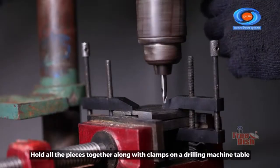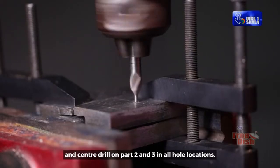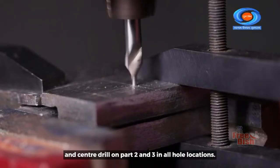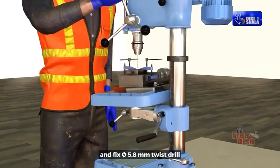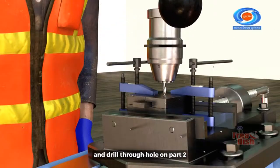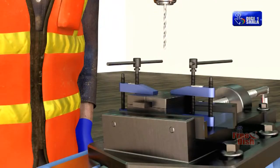Hold all the pieces together along with clamps on a drilling machine table and center drill on part 2 and 3 in all hole locations. Remove the center drill from the drill chuck and fix a diameter 5.8 mm twist drill and drill through hole on part 2 to fix dowel pin without disturbing the position of the job.